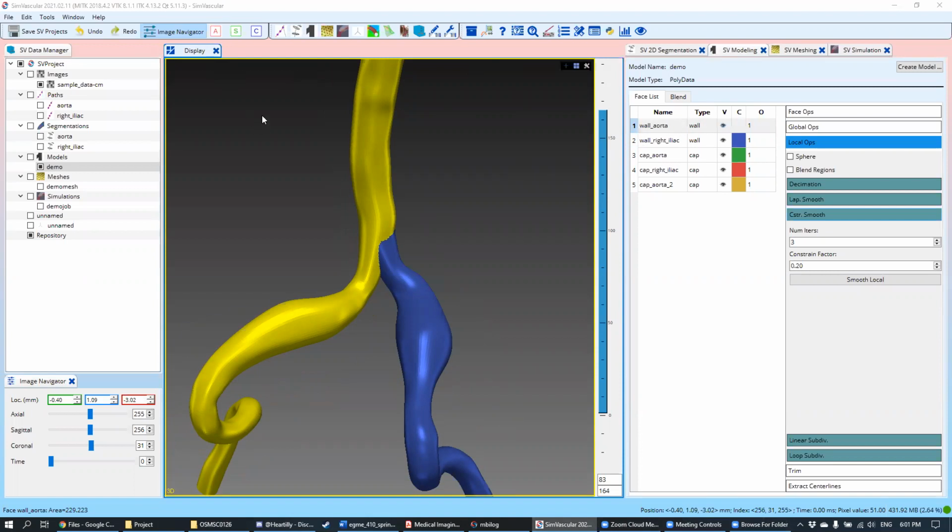Okay. All right. And so that's smoothing. Strictly speaking, it's not required. If you do a good job with your model, you can probably produce a decent mesh without any issues. But the smoothing does make things go a little bit smoother if you have some tough junctions there.